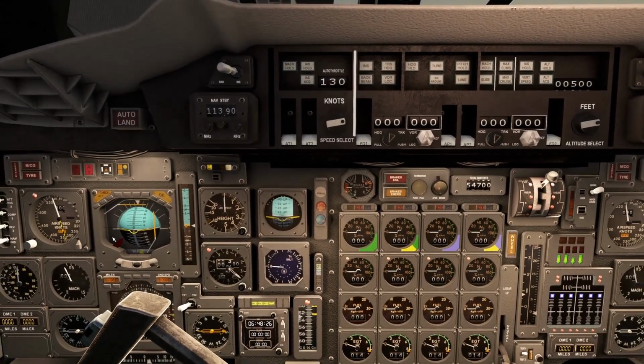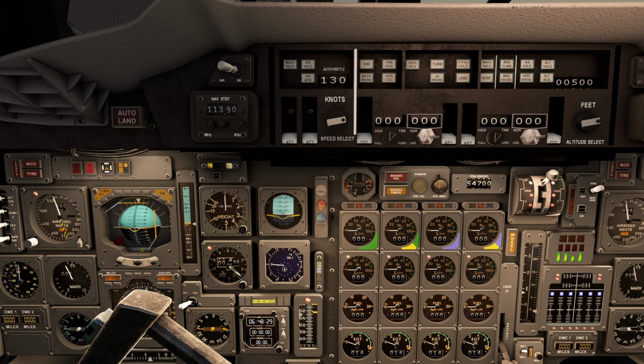We have to program our autopilot and FMC. FMC again is not that important, but still it has to be managed. We're gonna put on our first speed that we're gonna achieve with auto thrust, 250 knots below 10,000 feet, and we're gonna also put in 10,000 feet as our first desired altitude. By clicking you can change what you're changing. 100 feet is going to be important later on, but now we just want to have 10,000 feet.